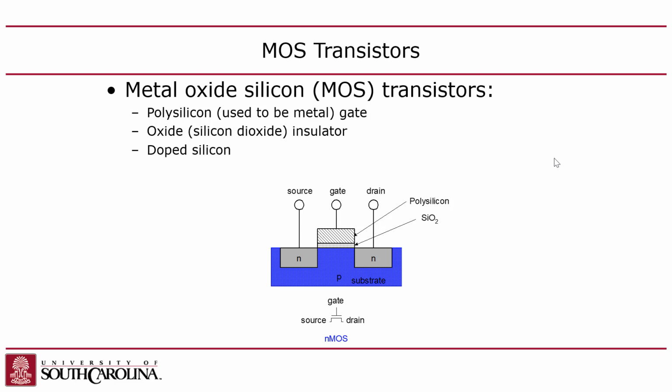So these are the layers. You end up with a substrate. Now, the substrate is basically the chip, the whole chip, the body of the chip. As I mentioned, you start out with a silicon ingot that you grow, and then you slice it into wafers, which are discs, right? Then those discs are sliced up to become individual chips. But before you do that, you dope the entire wafer.